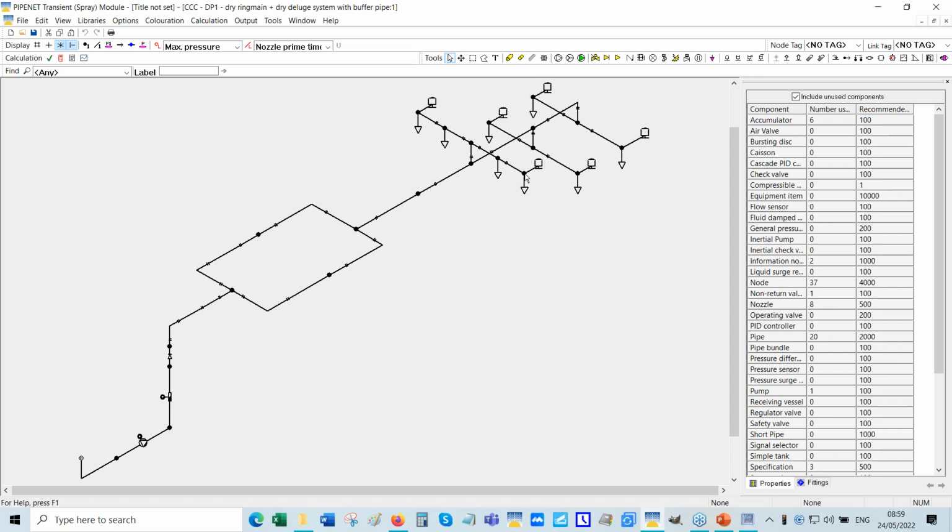Basically, all this means is that you do not end the range at the last nozzle. You extend that a little bit. See, that means air is trapped in the extension pipe. It doesn't make any difference because all the pipes are dry anyway. So when the system gets primed, that has a cushioning effect. You can model that with a dry pipe too, or with an accumulator.